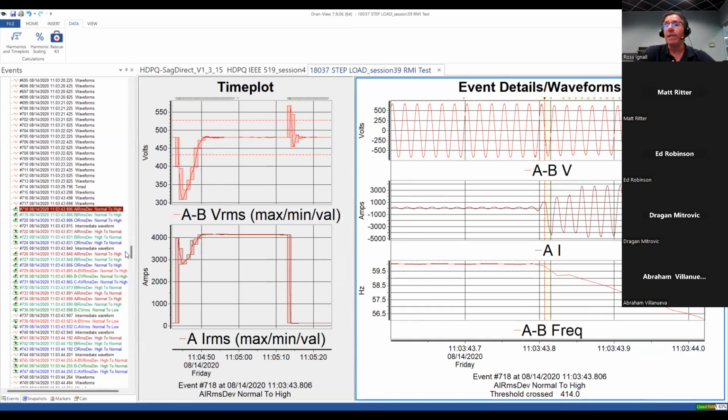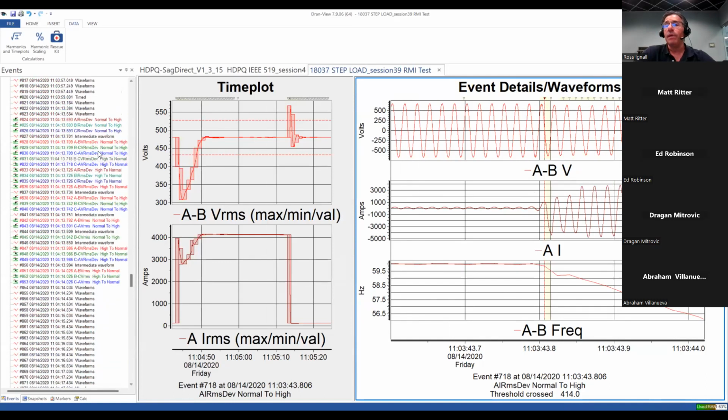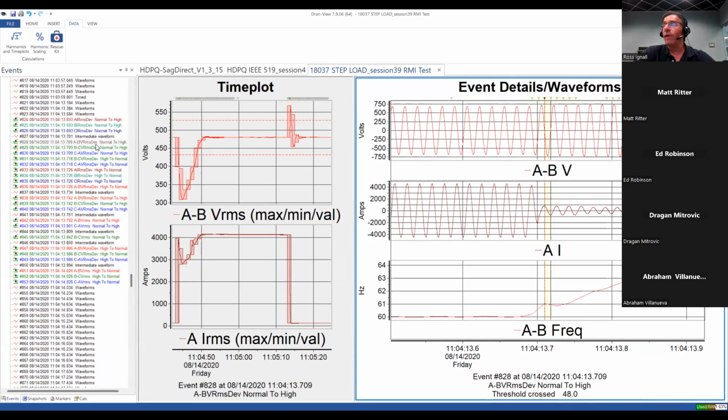Anyone that I select, I can go down and look at. You can see what the cycle-by-cycle frequency is. You can see the load turns off here, and you can see how my frequency drifts up at the output of that generator, that UPS, whatever they were looking at. Okay, thank you again for correcting me before.